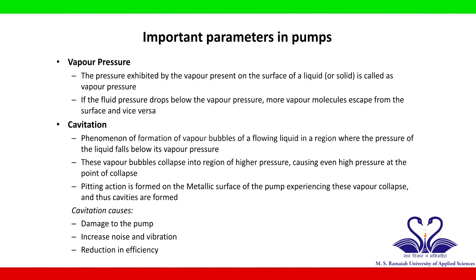Pitting action is formed on the metallic surface of the pump experiencing these vapor collapse, and thus cavities are formed. Cavitation causes damage to the pump, increase in noise and vibration, and reduction in efficiency.